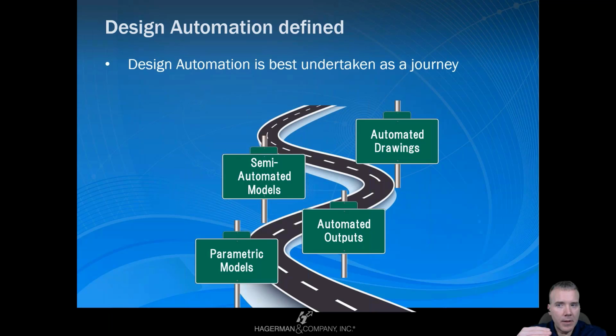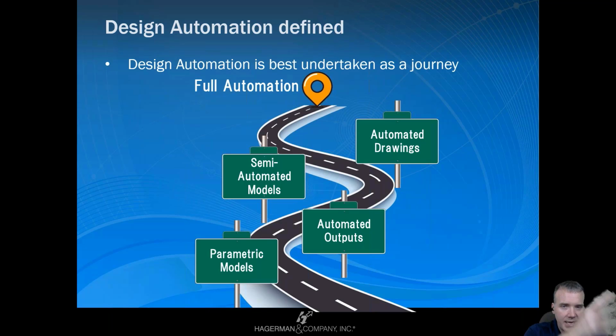Right? But the biggest step of all, in my mind, is the last one, getting to full automation, where you can place your design inputs into some interface and then press a button. And then after a few seconds or a few minutes, the end result is you have the outputs: PDFs, DXF flat patterns, STEP files, bills of material, right?